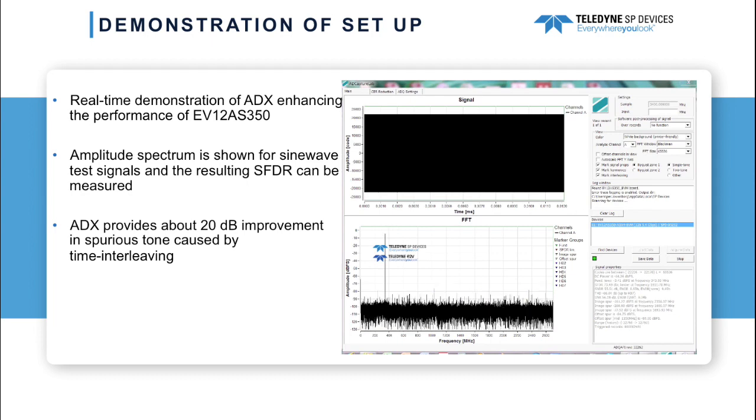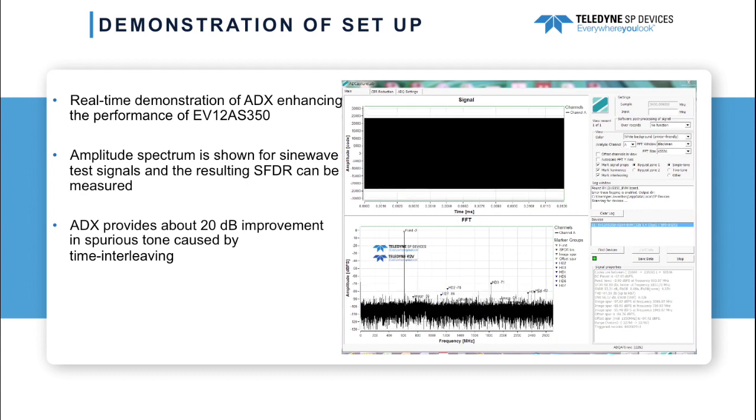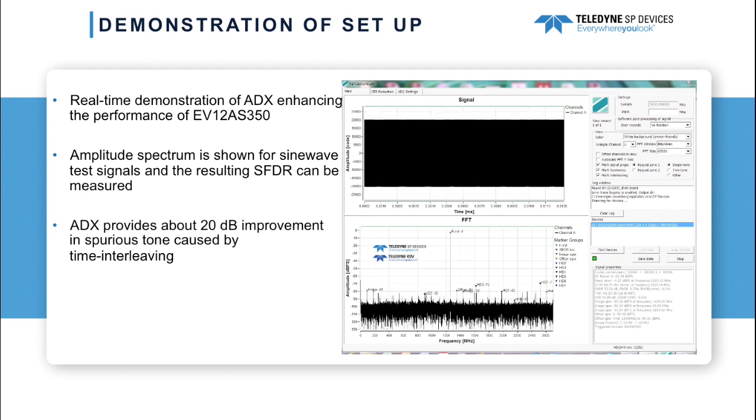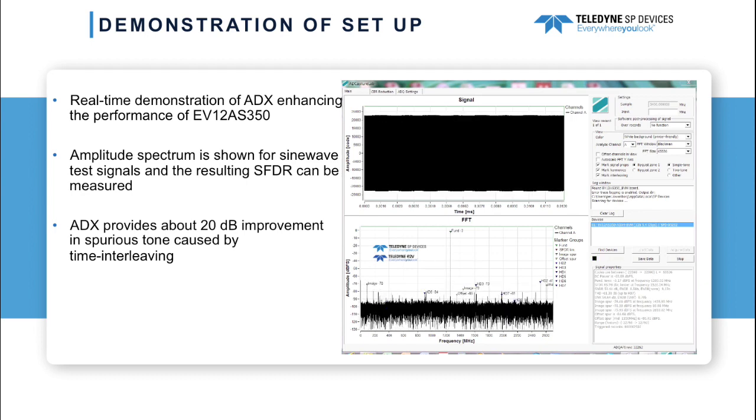We will look at the amplitude spectrum of the ADX4 output signal for a few input signal frequencies. Data is collected repeatedly, and from the measured amplitude spectrum, one can see that interleaving spurs are below 70 dBfs across the entire sweep. When the aliasing spurs reach such low levels, noise that is uncorrelated between different ADC core references causes small fluctuations in the aliasing tone levels.